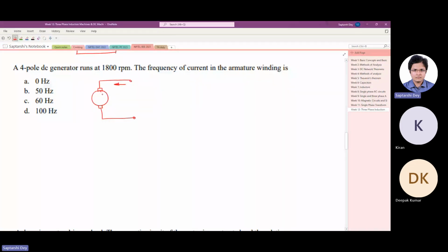That's it's a DC motor. But if you look into the armature of a DC motor, the current is AC. In fact, except for reluctance machines, there is no machine, I believe, where the armature current is DC. At least I cannot think of any right now. Armature currents are AC. In a DC motor also, the armature currents are AC. Now, if the current that is entering the armature is DC, how does it become AC in the armature? Any idea?